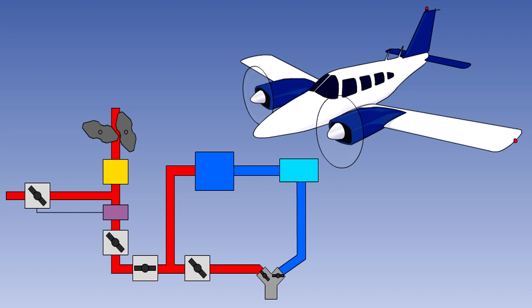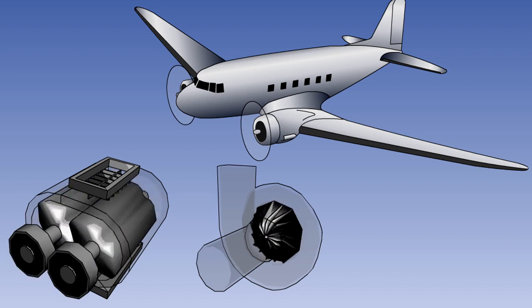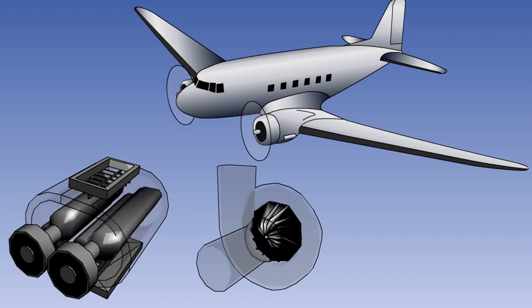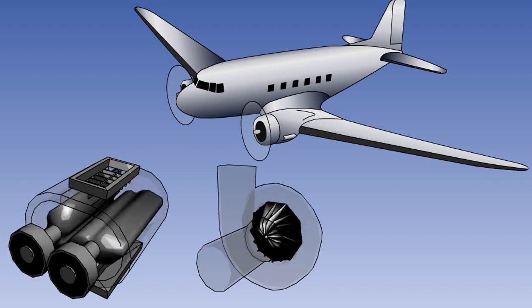In this lesson, you should have learned that most aircraft have a pneumatic system of some sort. On light aircraft, it usually consists simply of ram air, heated by either the exhaust gases or by a combustion heater, being used to warm the cabin. On larger aircraft, where the air is required to supply a pressurization system, it may be supplied by a cabin supercharger, or engine bleed air may be used.